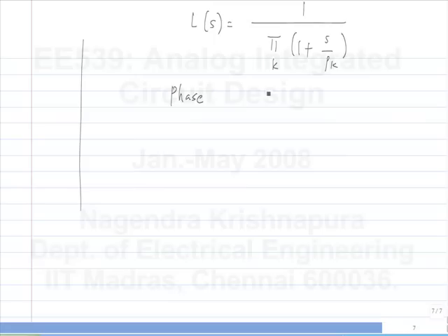But yeah, the concept of phase margin is based on what you're saying, that if gain is 1, you look at the phase, if it's more than 180 degrees, you say it is unstable. But I don't know if there are exceptions to that. Okay. So if you have an all pole system, that is definitely true. If gain is 1 and phase is more than 180 degrees, it is unstable. And for an all pole system, the other way around is also true, because the gain and phase are monotonic. If the phase is 180 degrees and gain is more than 1, the other condition is also valid and it will be unstable. Okay. But when you have zeros and so on, I don't know if you can come up with a system where the gain is 1, phase is more than 180 degrees, but somehow the system is stable. I'll think about it.